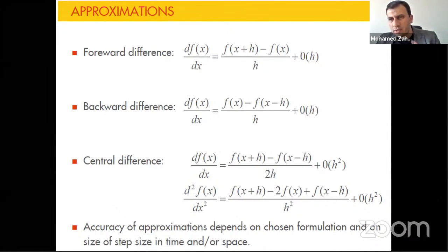Then the reservoir engineer starts to build what we call upscaling, which means reducing the number of cells in the simulation. By reducing the number of cells, we are maximizing the step size. Some people run the models on a monthly basis, some on an annual basis. By increasing the time step or the size of the grid, you are increasing the truncation error. This is another error coming into your calculation from nothing, just because of upscaling or increasing the time step. So this is really important.